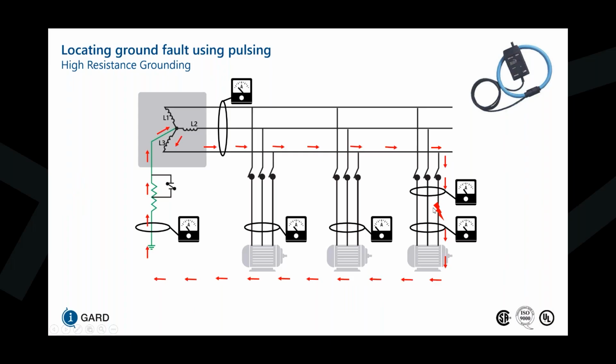So this is a very effective way of detecting and locating a fault while the entire system is still energized. We haven't de-energized anything, so there's no downtime, and then they can have a planned outage to address this first ground fault. It's always important to address these ground faults and just not hold the first fault in the system for an indefinite period of time, because the possibility of a second fault occurring on another feeder on another phase could create a phase-to-phase failure, which is unwanted.